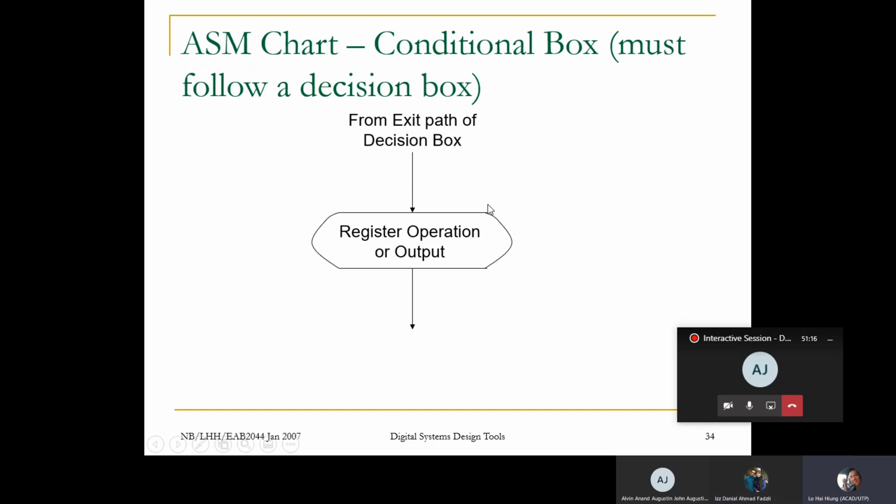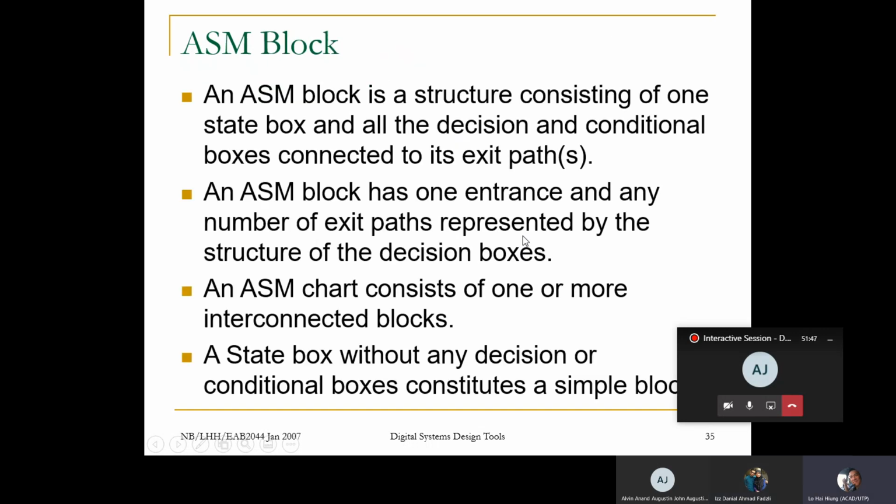What is described inside the conditional box is the register operation or output. So it is essentially a special type of state box, but it doesn't have a state name and it doesn't have a state assignment. It does carry all the register operations and the output signals. So far, so good? Yep. All right. So what is an ASM block?